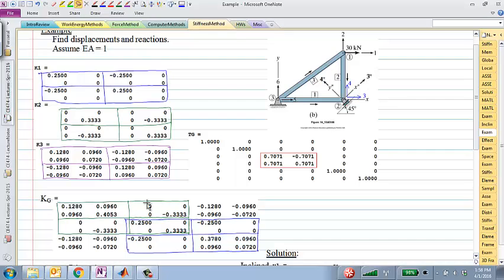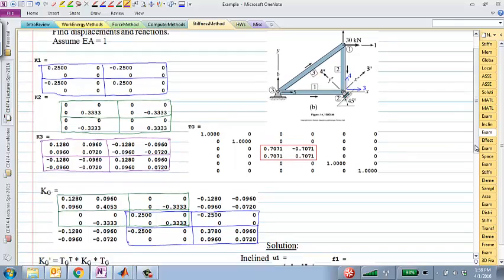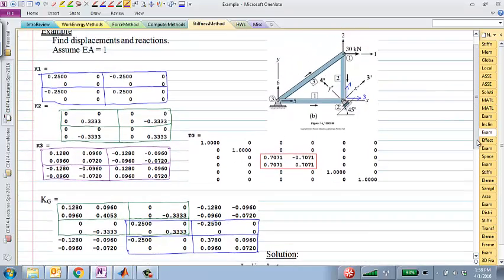So that's the stiffness matrix from the second element. That's components from the first element. And finally, we have elements from element 3, which is connected to nodes 1 and 3. So that would be degrees of freedom 1, 2, and 5, 6. So this particular purple matrix would actually get split into two different locations, just like the hand exercise we did maybe a couple lectures ago. It would go to 1, 2, and 5, 6.